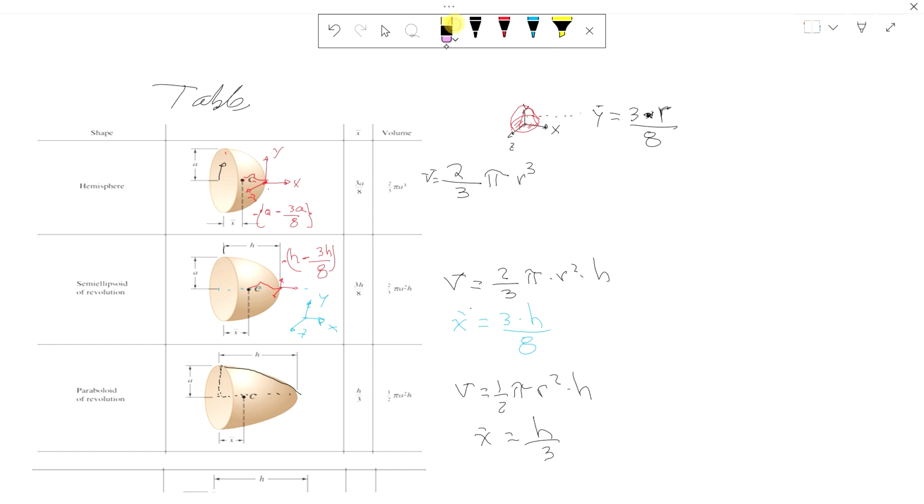Okay, so I don't want to have all this in the notes because I don't want to confuse you once you open the notes by yourself. But just to make sure that you know where your base reference is. In this case, we're referencing just that centroid. This is the number 3a over 8 because our 0 starts here. If they're asking you for this length, that's what I'm getting at. Between this centroid and this end is a minus 3a over 8.